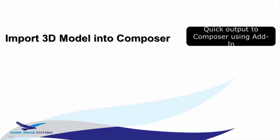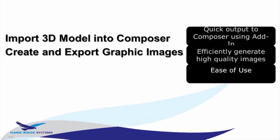So let's kind of do a quick overview of what we had done and what we covered. First, we saw how we imported a 3D model into Composer, right? Saw how SOLIDWORKS does it, and how we can also do it in Composer as well. The different options, and how it pulls off of the default document properties. All in all, you can probably do it in less than 20-30 seconds, fairly quickly. Next, we did the actual creation and exporting of the actual graphic images. So, ease of use and how we created those images going from A step to B step, and then how we generated those high quality images by using the workshop in multiple views.